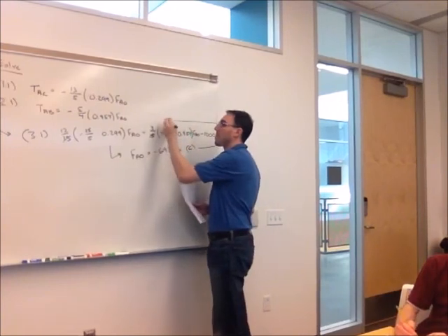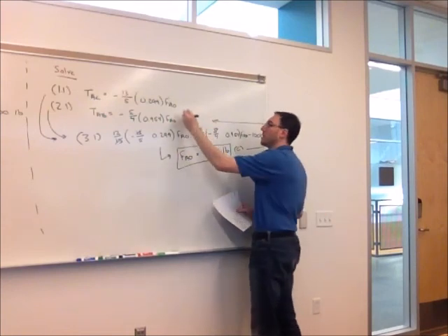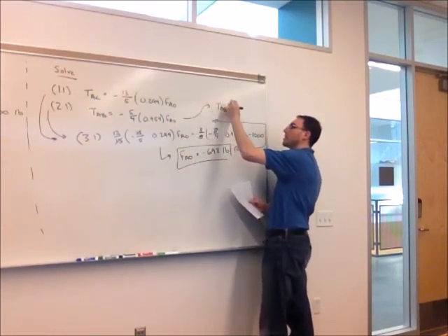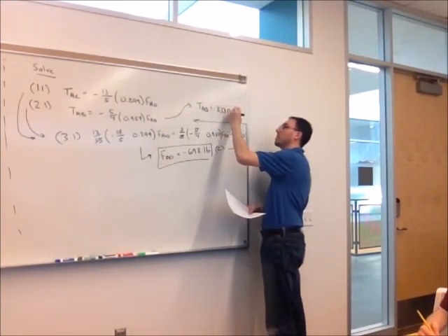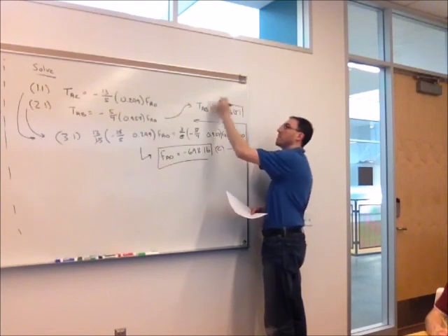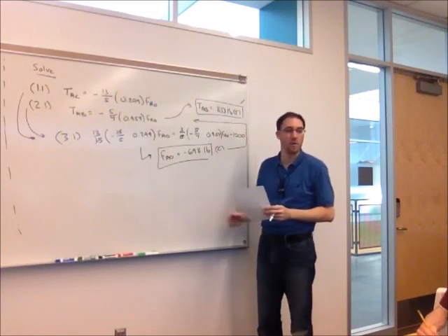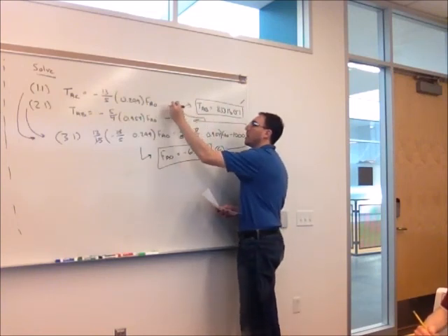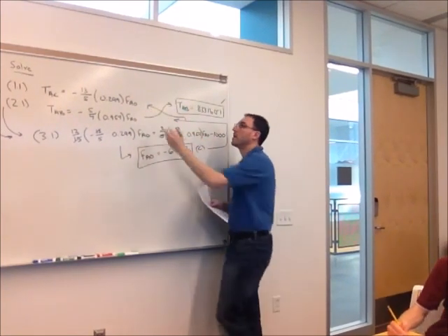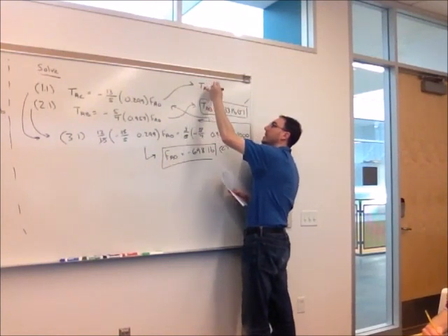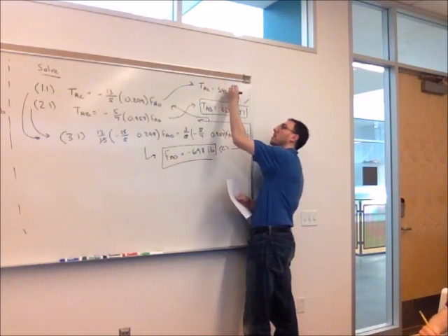So now that we finally have a number, I can put this number into equation 2.1 and get out that the tension in AB is 833 pounds. So it's in tension. Again, a quick check. It has to be in tension, so at least we can't rule out our answer yet. A lot of arrows here, but also put this negative 698 into equation 1.1 and get out that the tension in AC is 542 pounds. Also tension.